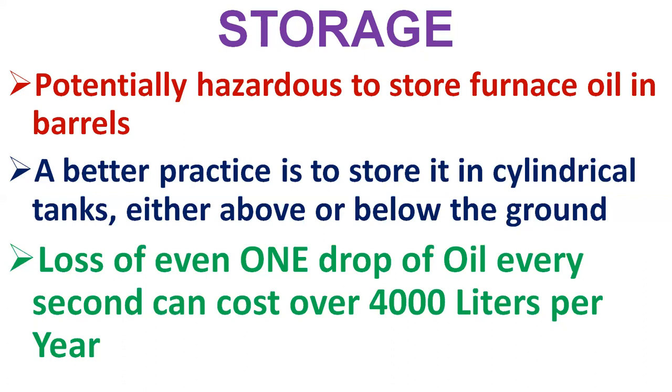The sizing of the storage tank facility is very important. A recommended storage estimate is to provide for at least 10 days of normal consumption. Industrial heating fuel storage tanks are generally vertical mild steel tanks mounted above the ground. It is prudent for safety and environmental reasons to build bund walls around tanks to contain accidental spillages.